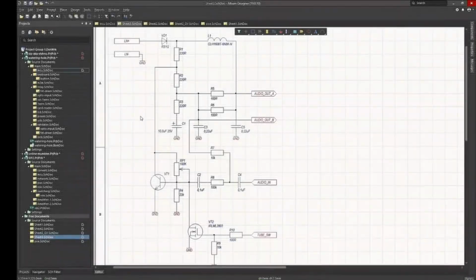Mistake number 1, reading by components, not by functions. The first and most common mistake is reading a schematic by its elements rather than by its functions. That is, a beginner sees a resistor, an inductor, a capacitor, a transistor, while an engineer sees a voltage divider, a filter, a transistor switch. And until you understand what a stage does, the schematic will seem frightening and chaotic to you. And a question for you: when did you first realize that a schematic is not just components but a process? Do you remember that moment?